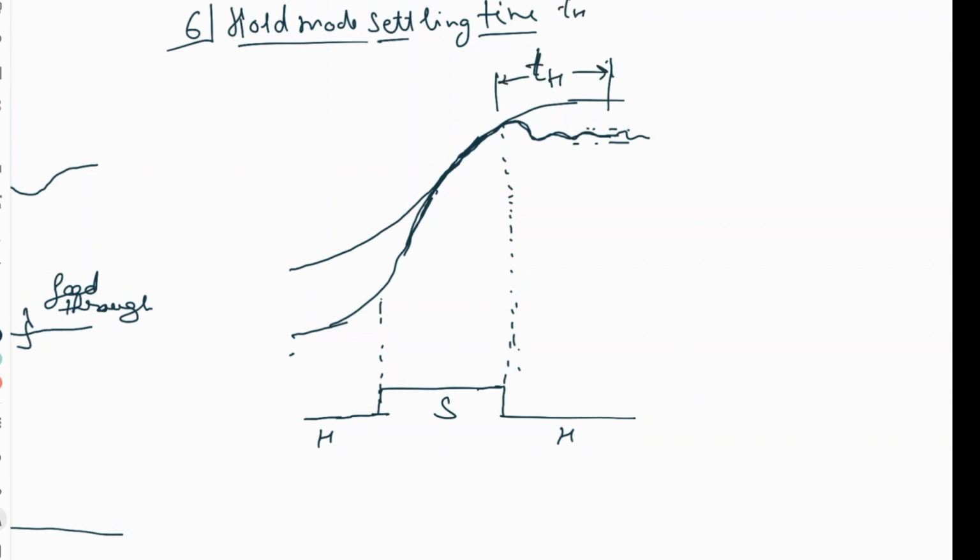The seventh one is the droop. This is basically a constant drift of the output voltage due to the charge leakage from the hold capacitor through a switch or output buffer. When we say it's holding, there will still be some leakage happening, as nothing is perfect. Because of this there is a small amount of voltage drop.